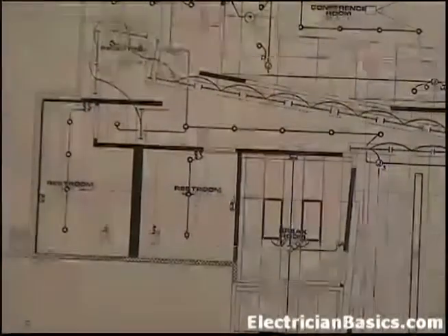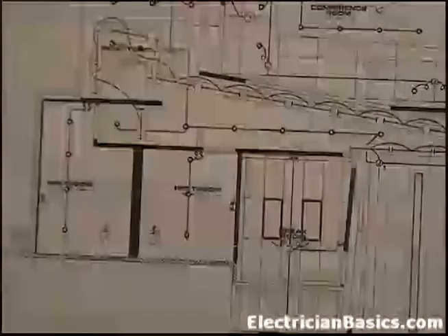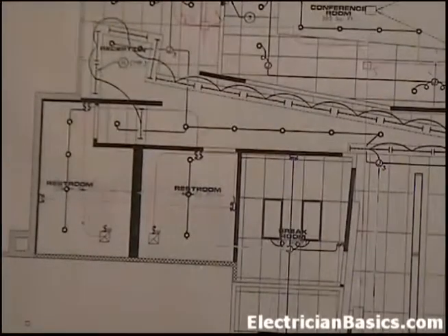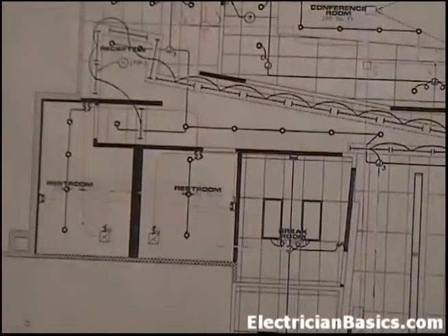The drawing that the architect draws just shows everything on the circuit that has to be connected together. It's up to you to choose the route, because you're going to look at it, you're going to find out all the structural members and how the walls are built, and you'll find the best way to do that. So the architect is just basically supposed to show you all of these things are on this circuit and they're controlled by these switches, and these are the locations. So it's up to you to go through and make this plan work the best way. And that is why you are going to redline it, so that you show what you did, so that the customer can look at it and understand it.